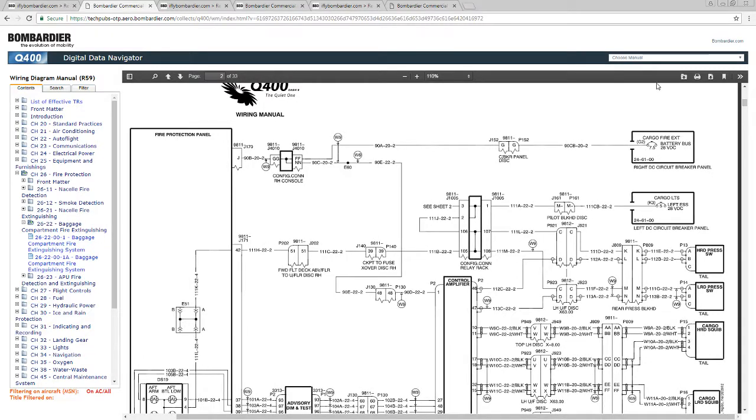And here we go. If you look right here, here is K3. This is our cargo lights. It's our left essential bus. And we've got this wire coming from the circuit breaker K3. And it moves here through the bulkhead and over here into the relay rack. And now we've got our wire. Again, we're chasing it over to number 42. So if I look through here, I'm going to keep working through all these different components. Now here we're at 42, and this is indeed the fire protection panel.